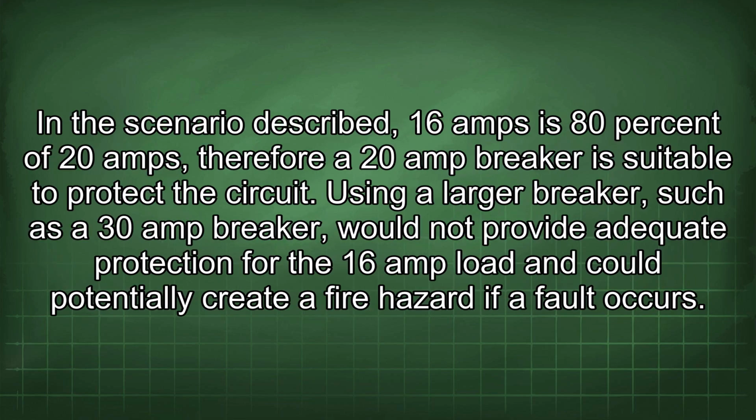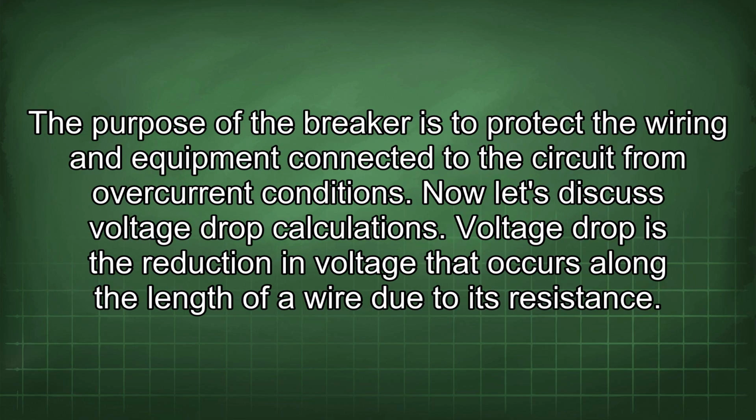In the scenario described, 16 amps is 80% of 20 amps, therefore a 20 amp breaker is suitable to protect the circuit. Using a larger breaker, such as a 30 amp breaker, would not provide adequate protection for the 16 amp load and could potentially create a fire hazard if a fault occurs. The purpose of the breaker is to protect the wiring and equipment connected to the circuit from overcurrent conditions.